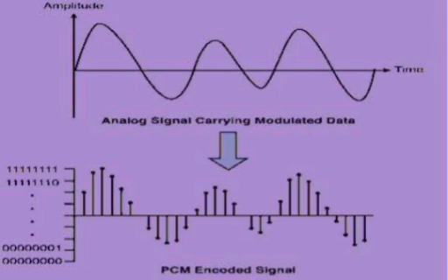In FDM, we divide the whole bandwidth of the channel into small segments and allot them to different users so that they can access the channel at the same time by using their allotted bandwidth. In TDM, the whole time slot is divided among different users so that at a time only one user is accessing the channel. Bandwidth requirements in TDM and FDM are almost the same for the same number of users.